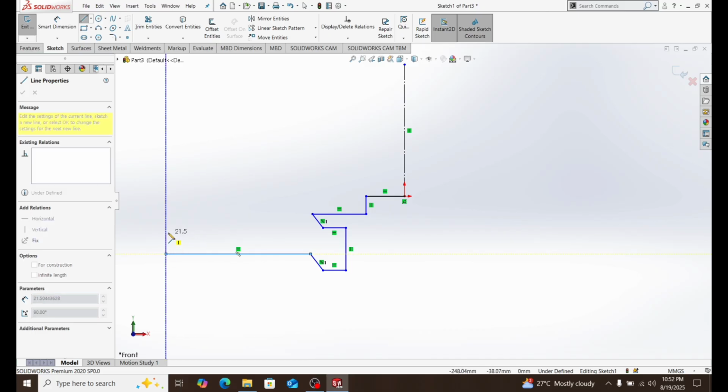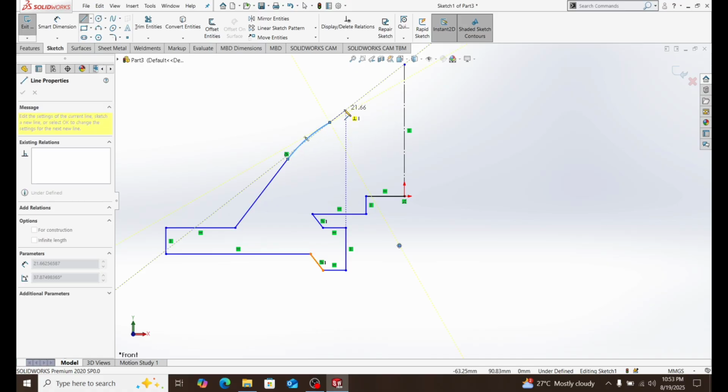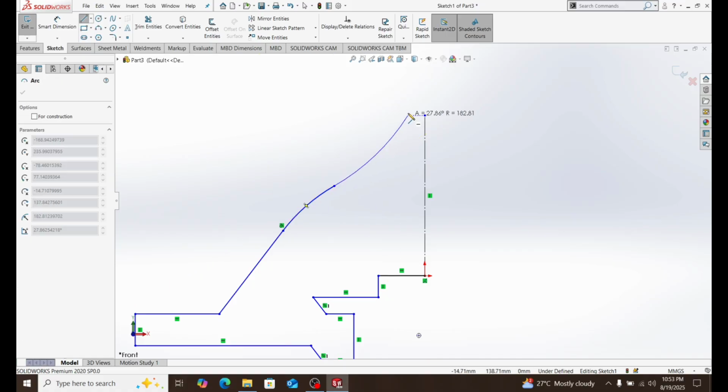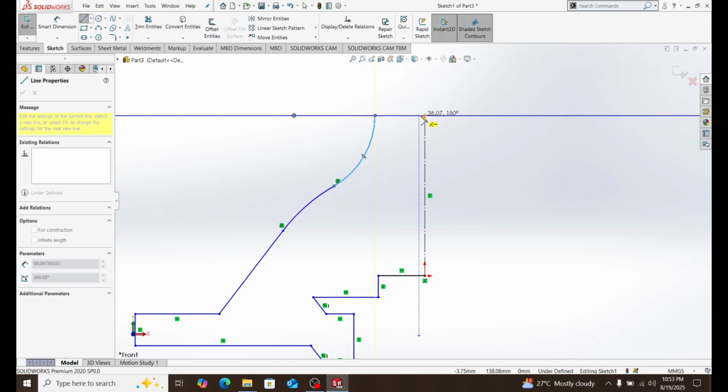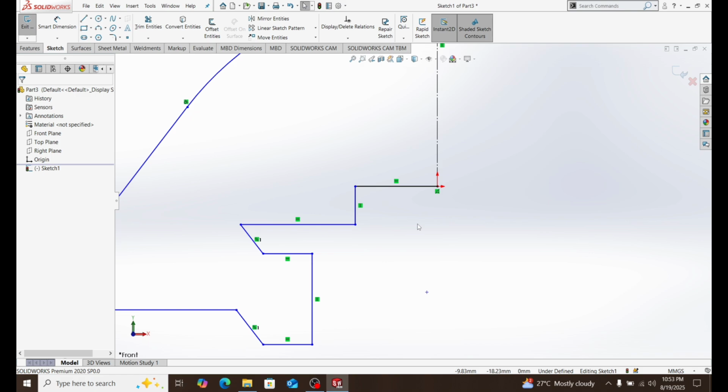As we are making it from front plane, we can extrude it. So we may reduce some steps instead of doing 3-4 boss extrudes, etc. Yes. For selecting these arcs, just go to this below point again, so you can select the arc. Now we have completed this sketch.